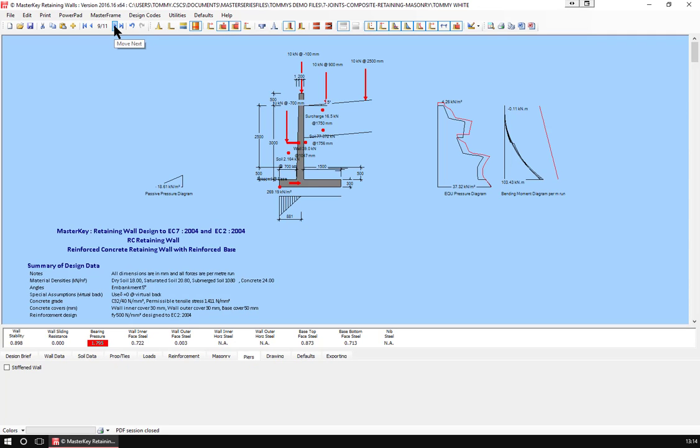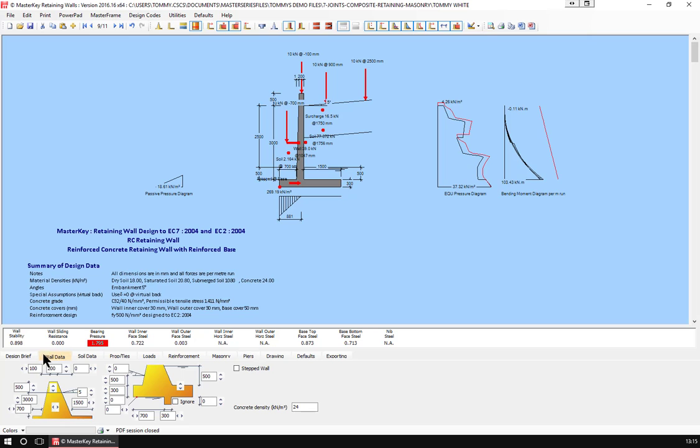And then finally we come back to my crazy wall. So crazy walls, this is where we're going to get into real depth and spend a bit of time looking through the parameters that we're able to work with and use in the retaining wall program. So obviously wall data, we can see it's got 100 taper up to a 200 wide.